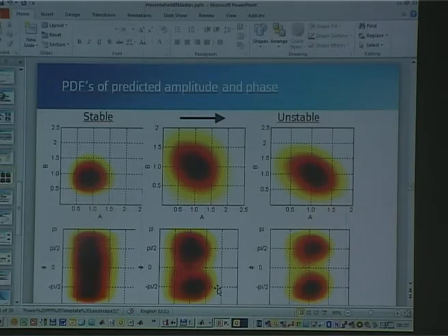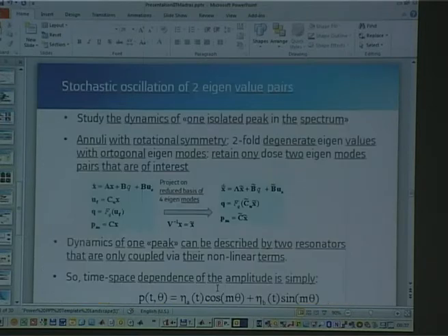So now we understand that what the experiment shows corresponds with what our numerical simulations show, but we still don't really have an understanding of why this is and what's behind it. We have this whole model, but there are so many states, and something comes out, but what is really the key behind this? Well, if you look at the spectra of this oscillation, you just see one peak, so it means one frequency. We know that for these two frequencies, there are 2 modes, one the cosine shape, the other sine shape. So basically, we should be able to reduce this whole system, with hundreds of states, to just 4 states of two oscillators with 2 mode shapes.